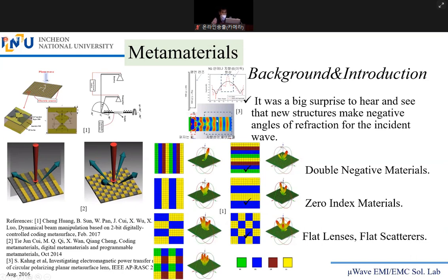You can see that away from the structure, approaching the far field region, this field region is a radiative near field region or Fresnel region, not the Fraunhofer region. But even in the Fresnel region, you can see the parallel wavefronts. Parallel wavefronts mean rays are in the same direction. Imagine the direction of rays is perpendicular to the wavefront. Wavefront and rays, like that. So please remember this.